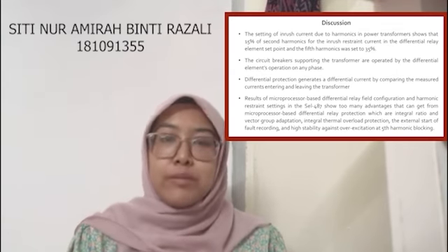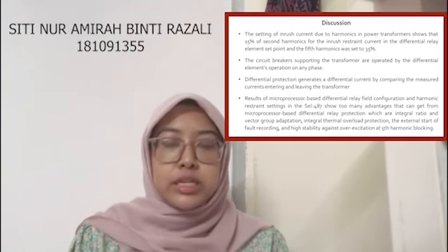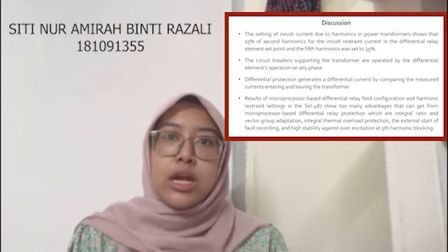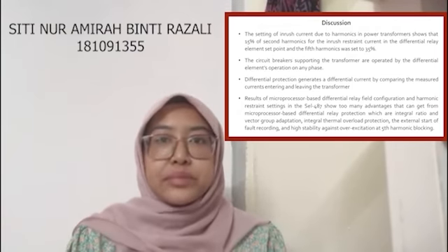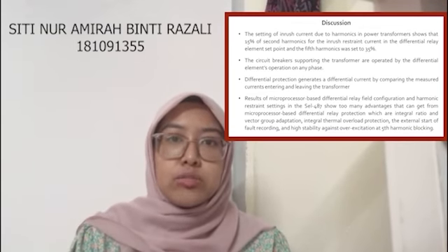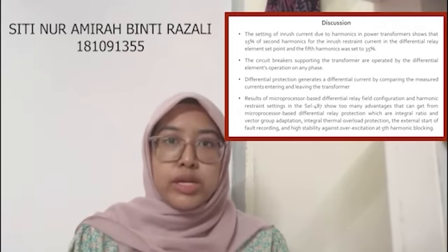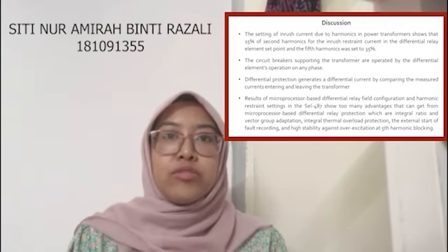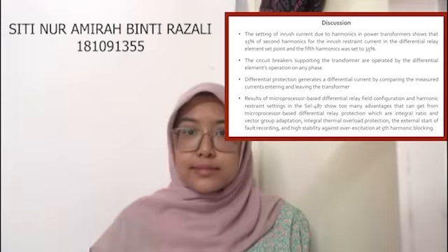For this application, the transformer energization produced magnetizing inrush current sufficient to activate the differential element. As a result, the differential relay operating current is 0 because the total current entering its primary restraint winding equals the total sum of the current leaving its secondary restraint winding.